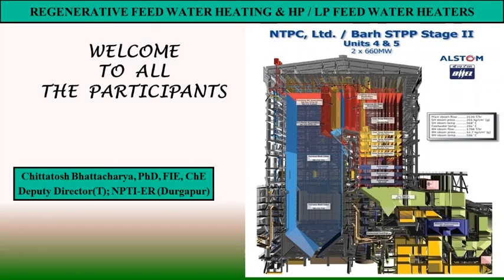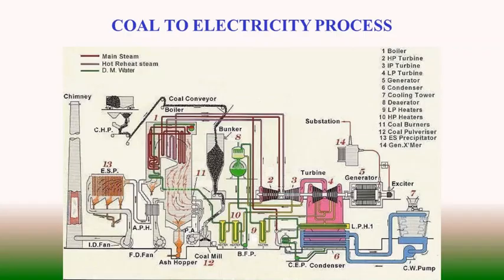But in a power station, the heaters utilized in the water-steam circuit for regenerative feed water heating are used in two segments. One is the feed water heating segment, another is the condensate heating segment, and both these segments together contribute to the regenerative feed water heating system.